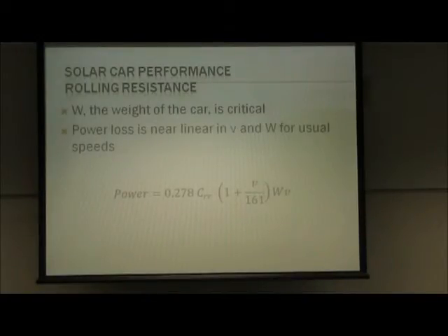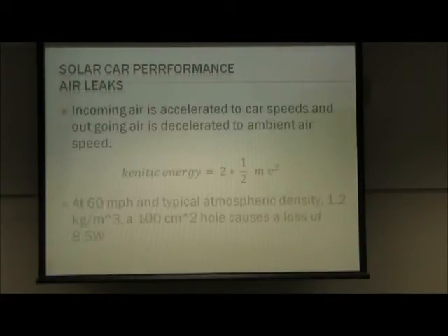But if half of our power at 40 miles an hour is approximately rolling resistance, that's about where the trade-off is. And rolling resistance is dependent on weight, and the 0305 car weighs 200 pounds less than the current car, in other words 2/3 of the weight. It's going to require about 2/3 of the power on rolling resistance, so you're going to be saving 1/3 of your power coming in. So weight is critical. That's why you try to reduce weight on everything you do.